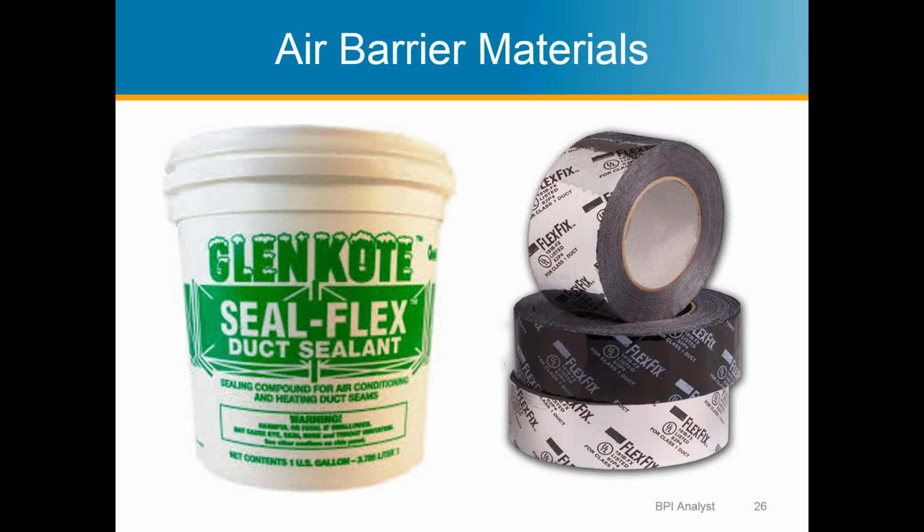And so these are primarily for ducts, but that's the point, right? Ducts themselves are an air barrier to the house. The ducts are part of the building envelope or the building shell because inside the duct is basically heated air or cooled air, that's conditioned air that's in the house. On the opposite side of the duct, a lot of times, at least the way we build, is going to be an unconditioned space. So you have to think of ducts as part of the building shell, no different than the wall.